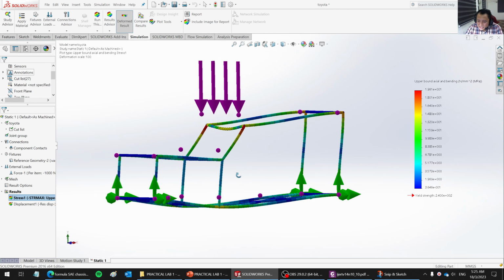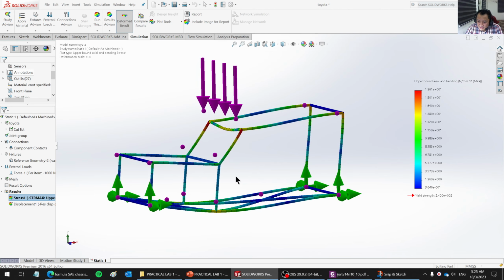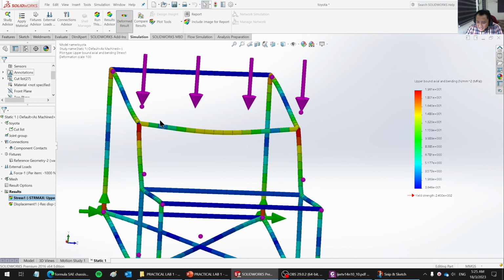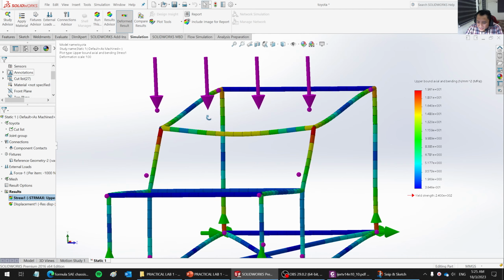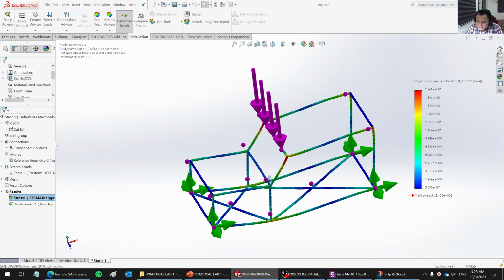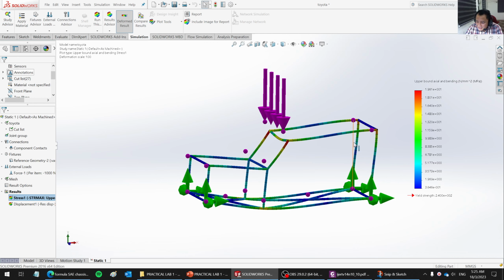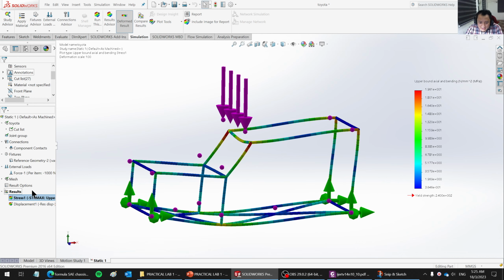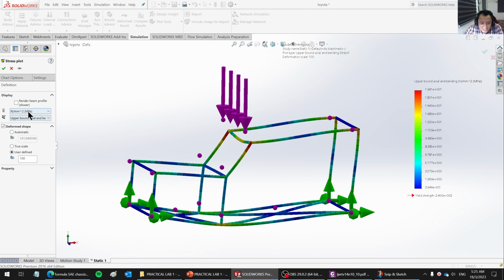This is done to help engineers solve problems. For example, I can see there's a lot of bending here on this roof frame. So this roof frame is not getting enough reinforcement. I cannot see that if I'm looking at a real deformation scale factor. So edit definition again, change a few things, megapascal, and then go to property